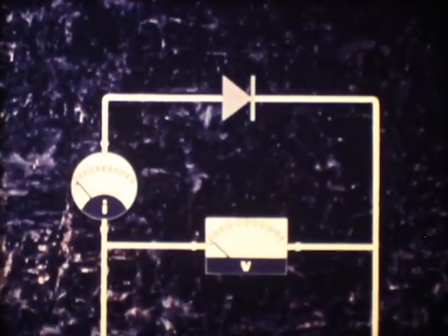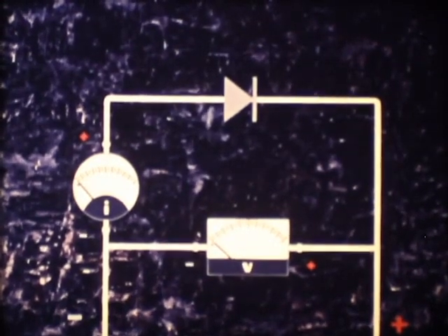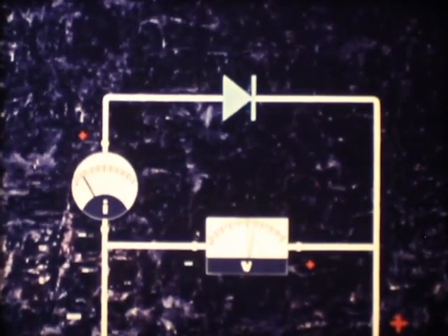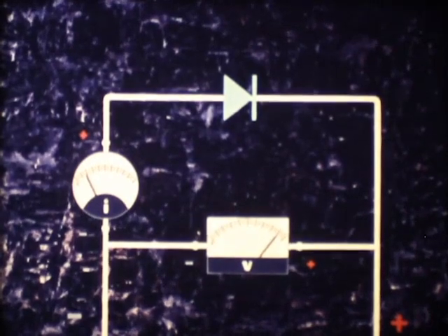By adding the currents flowing through the parallel combination of junction and resistance, the total current flowing through the diode can be found. The sum of these two characteristics gives the reverse characteristic of the diode. With a circuit such as the one shown, the reverse characteristic of the diode can be measured. A large change in voltage will give rise to a small change in current.